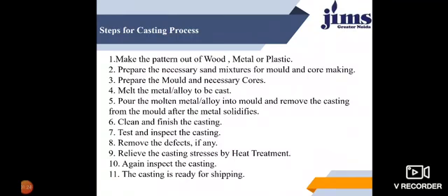Next step is the metal. We have to melt the metal with which we have to make the casting. So we take a furnace and we melt the metal. Next, with the help of a ladle, we have to pour that molten metal into the mold, and we have to fill the casting when it gets liquefied.